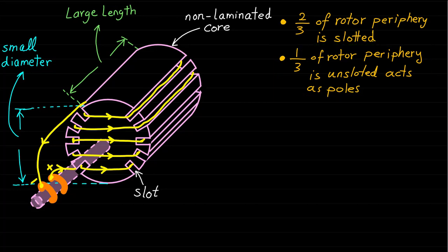Synchronous machine that uses cylindrical pole rotor type is usually used in high-speed applications because it is mechanically balanced, such as in turbo generators, which are driven by steam turbines. When the DC current flows through the field winding, the rotor generates DC field and becomes an electromagnet. That means the rotor becomes a big magnet with north and south poles.